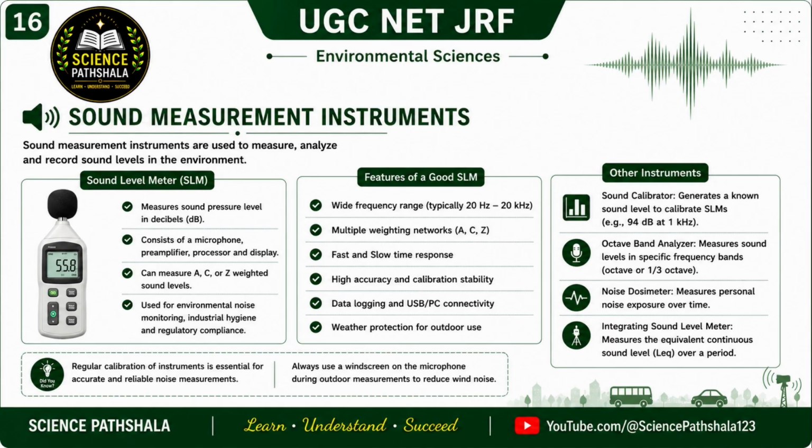Now let us look at some other important sound measurement instruments. First is the sound calibrator. A sound calibrator generates a known sound level such as 94 decibels at 1 kHz to check the accuracy of sound level meters. Second is the octave band analyzer. This instrument measures sound levels in different frequency bands and helps identify dominant frequencies in noise.